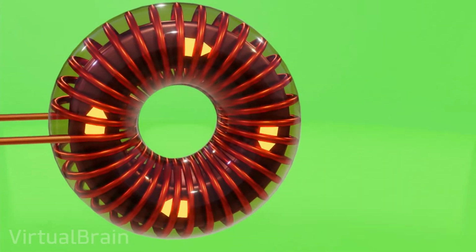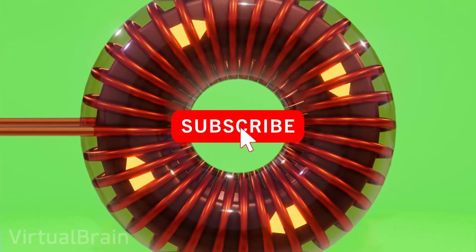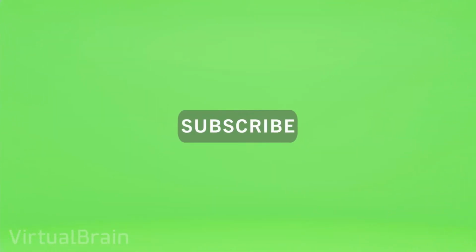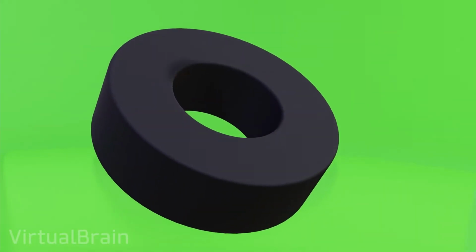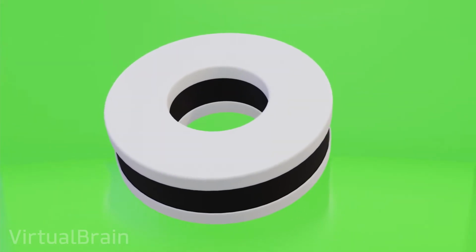But this is not all about toroidal transformers. We haven't even talked about the secondary winding yet. So let's take a look at how a toroidal transformer is made from scratch. First of all, we will have a toroidal core which generally has a coating such as a nylon cover to prevent it from having direct contact with the primary winding.